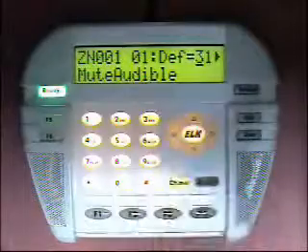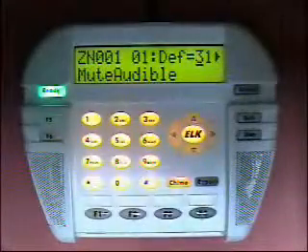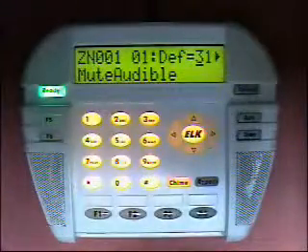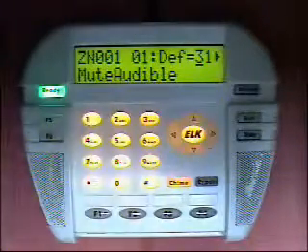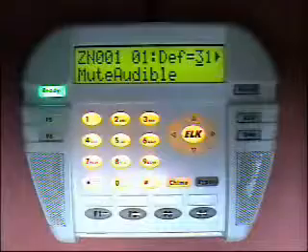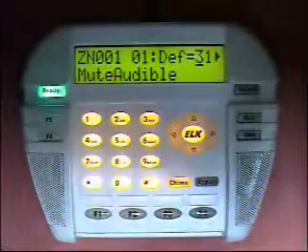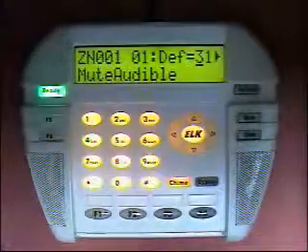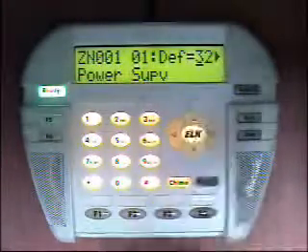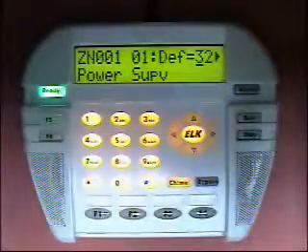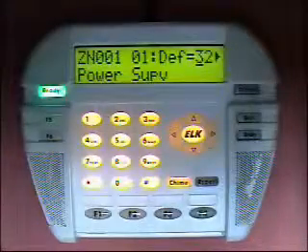This is a zone input that when it is activated or violated, it will mute all the audibles. This is good for audio listening using third-party audio listening equipment where you want to mute the sirens. Power supervisory, if you have a remote power supply powering the system and you